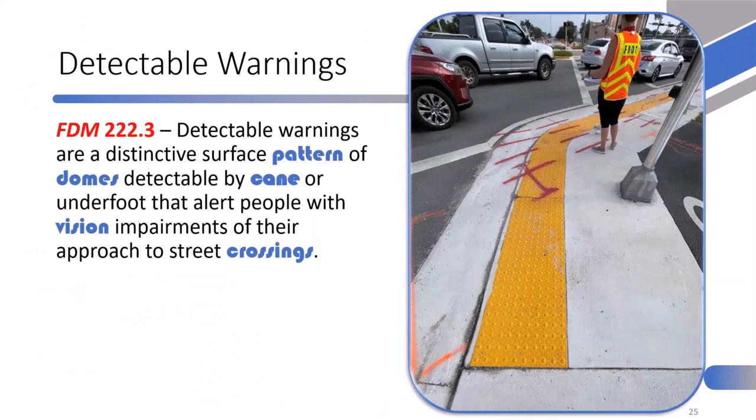Okay, this detectable warning configuration in the picture is nominally compliant with the criteria, but is it substantively the best solution that could have been provided here? And I would suggest to you that because of the wraparound nature of that detectable warning surface, it's actually communicating that in that wrapped corner is an appropriate crossing direction, when in fact it's not. So what could be done better there?